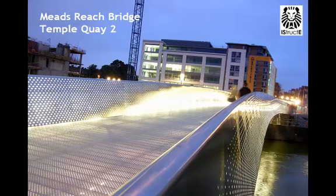This is a stainless steel stress skin footbridge, and for extra interest they took the stress plots from GSA and used those to work out what perforations they could get away with in the stress skin, so that they could then put lights inside the bridge, and you sort of get, at night anyway, a negative image of the stresses in the structure. It's very pretty actually.